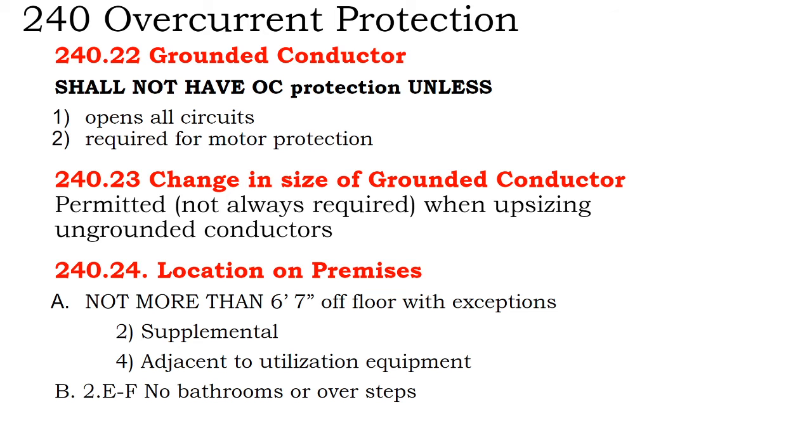Your breakers and panels should not be, your breaker switches should not be more than 6 feet 7 inches up off the floor. So you shouldn't have to climb a ladder or step stool to access a breaker or disconnect switch.